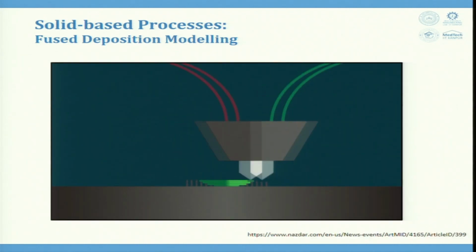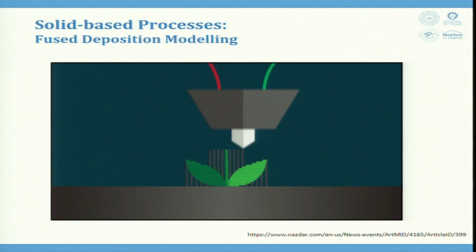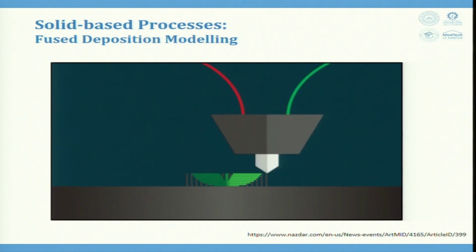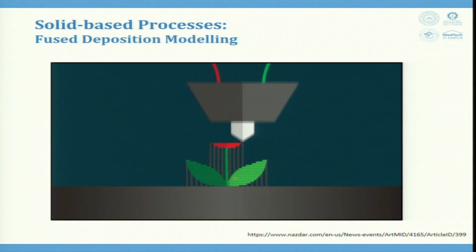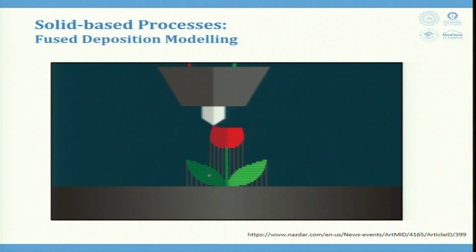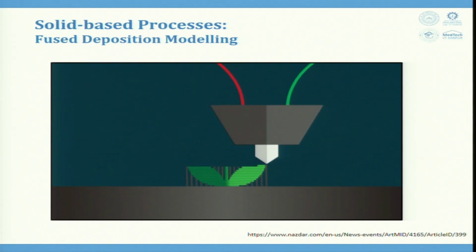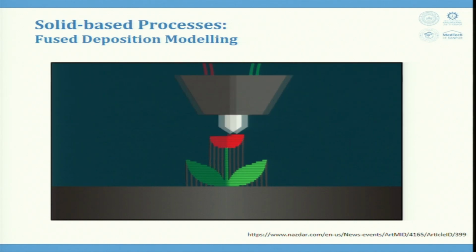Let us try to see the two filaments are connected, and we are trying to complete this here. Here both the filaments could also be form materials only. For example, the lower part is giving one color, the upper part is giving the other color. So, the two materials which we are using are not support and build materials, but both of them are build materials, and they are providing the color variation in the final print that we are getting through this process.